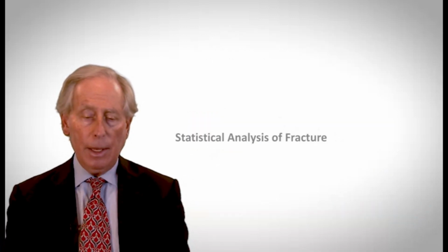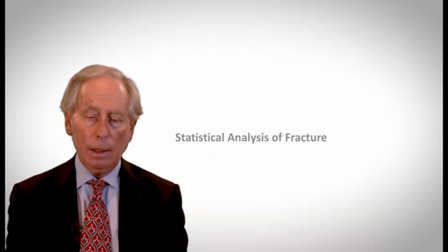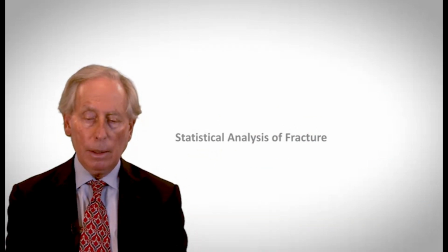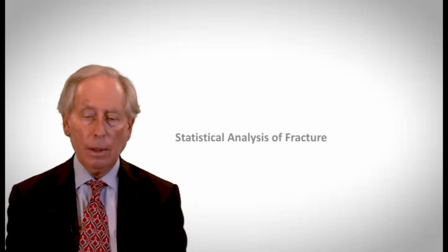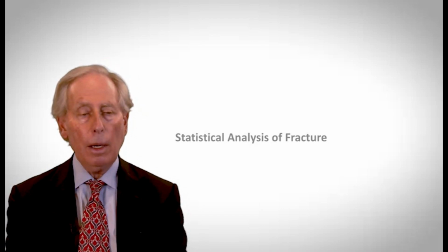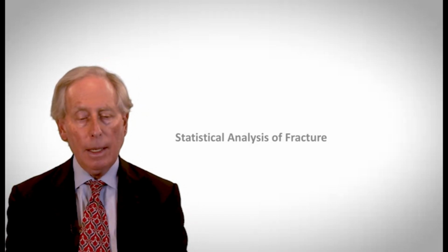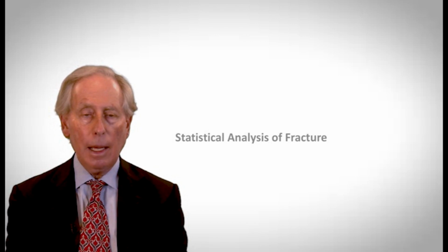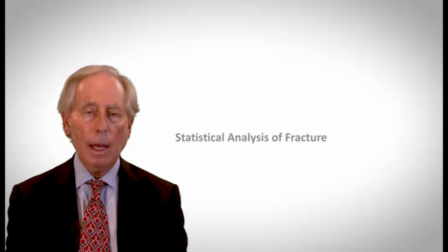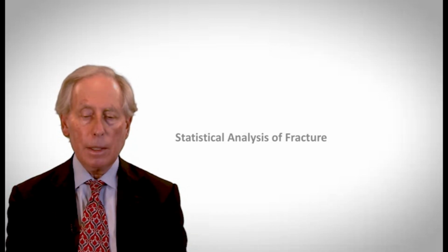The next section I think is particularly important, and one I want to focus on a bit, and hopefully I'll get some feedback from some of you on how useful it was. I think it's the most important part of the testing procedure, and that is, how do we analyze the statistics of failure from a small set of specimens to be able to understand and have confidence in the strength of my set of components.